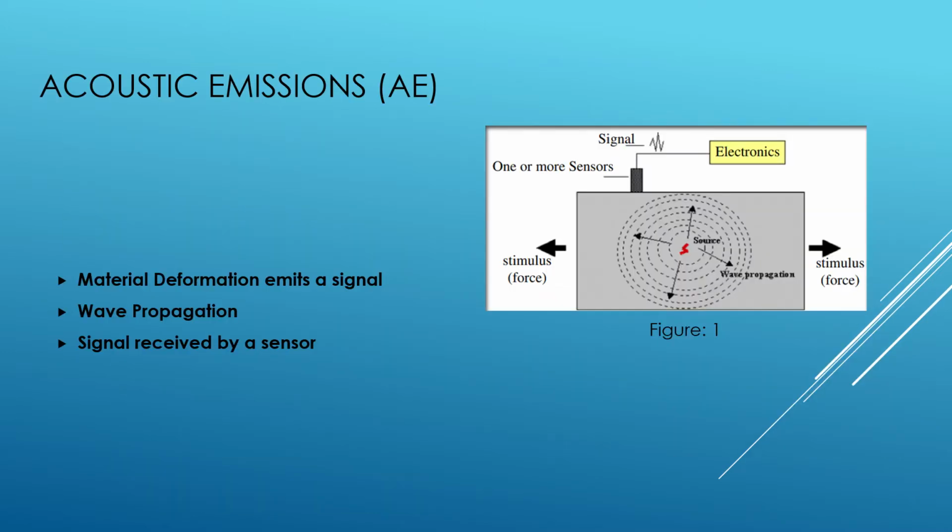Bridges and roadways are under constant cycles of stress as heavy vehicles drive over them. As the bridge goes into a state of stress, the materials such as concrete and steel emit a form of elastic waves. These waves are picked up and measured by sensors attached to the roadways. The acoustic emission system requires a material deformation from a source and a transducer that receives a stress wave signal. This makes it an ideal system, as a developing flaw in the material emits a burst of energy in the form of high-frequency sound waves, which are received by the sensor in place.